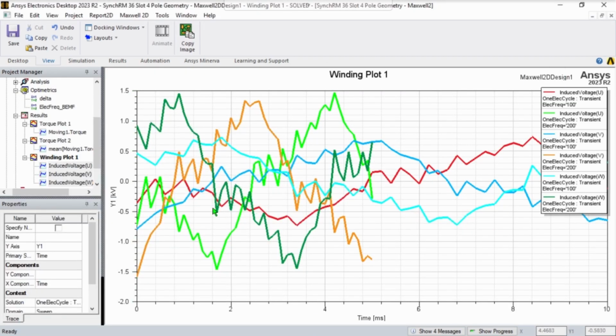And they're kind of overlapping each other, but basically this is the back EMF of both the simulations at 100 and 200 hertz. And you can see that the 200 hertz simulation is kind of squashed because since it was at a higher frequency, the period was over a shorter time, right? But what we're going to do with this is, maybe I can comment more, it's really ugly looking. It's not super smooth like an IPM motor.